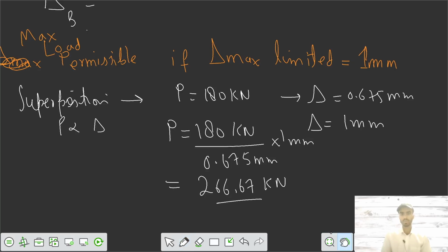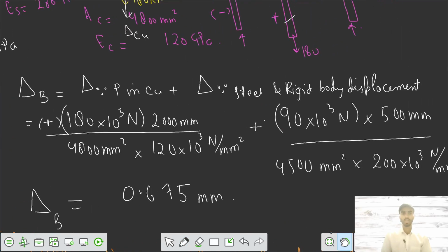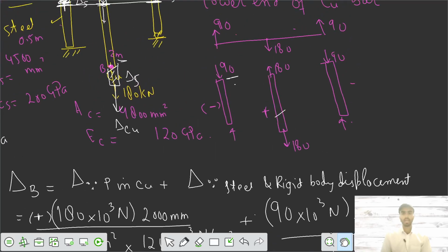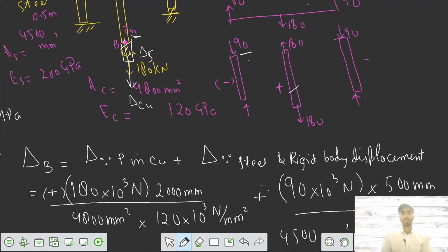Or you can also calculate it this way. If the question is conventional, like a 20-mark question, in part 2, taking the maximum force as P, you can get deflection 1 as P L by A E, the rest is constant, plus this one, which was P by 2.